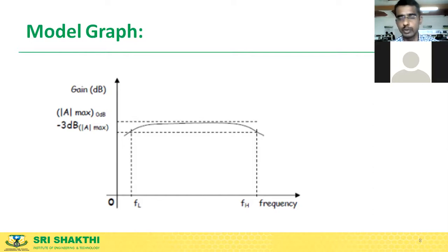Whatever is the input voltage, in most cases, 99%, the output voltage will also be the same. That's the uniqueness of the common collector amplifier. Though it is called an amplifier, the voltage gain is unity, right? So whatever is the input voltage, you're going to get it at the output.